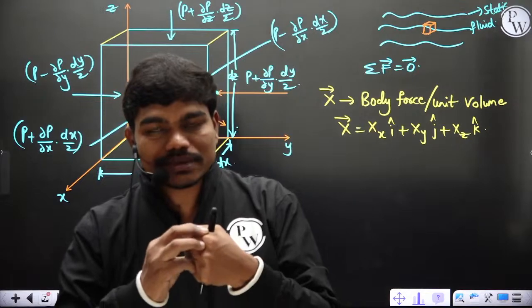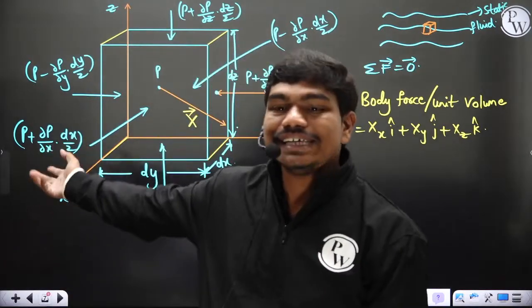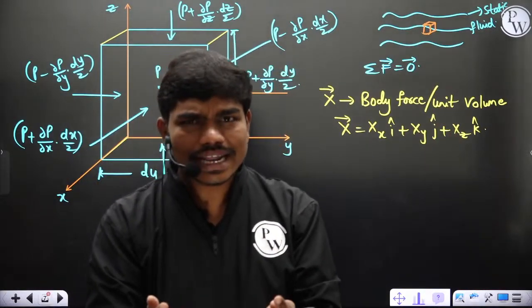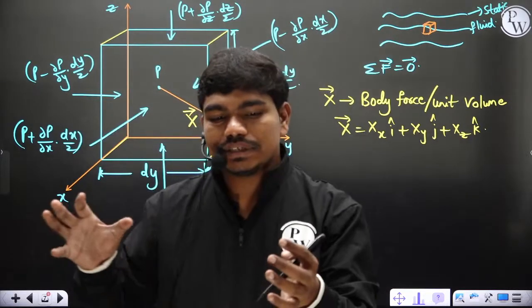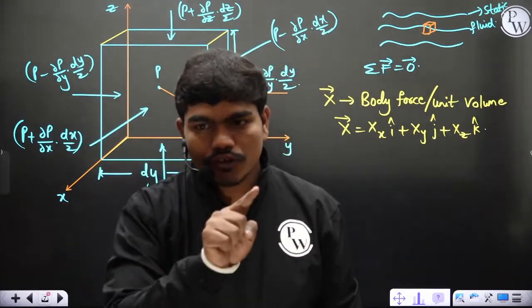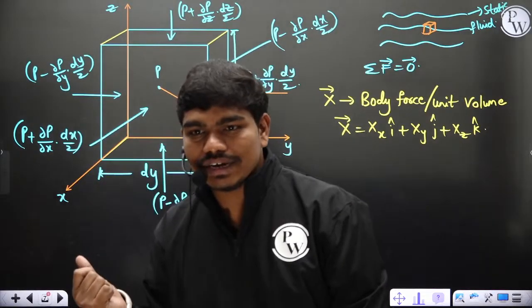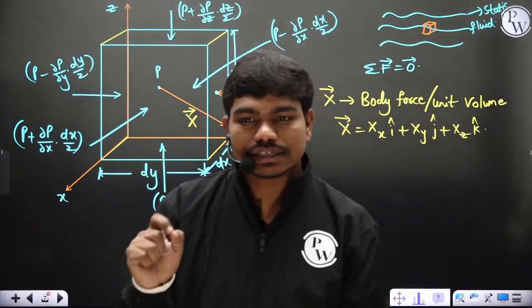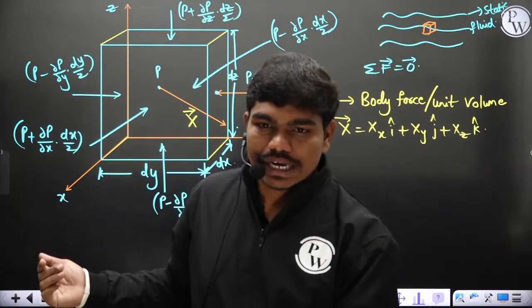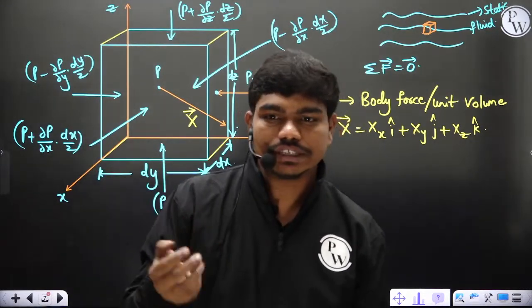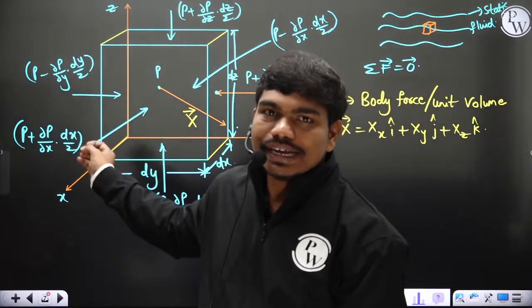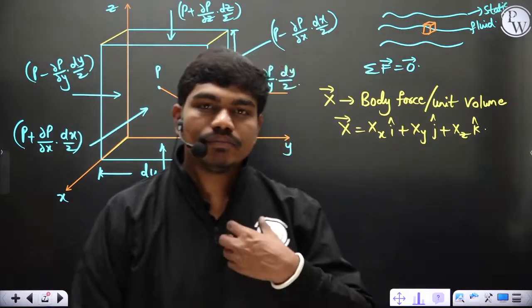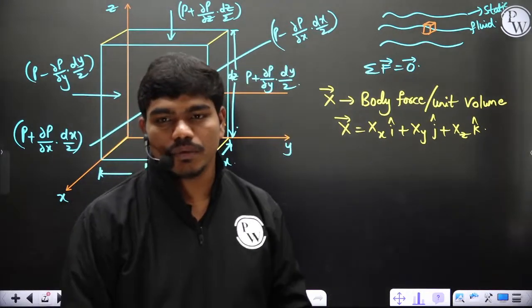Okay, so whenever the fluid is in a magnetic field, for example, let us suppose this is some molten iron. Let us suppose I have taken a big ladle of molten iron, then let us suppose I keep some magnet close to that. This static fluid of molten iron is exposed to some magnetic field, yes or no? Then the magnet will exert this magnetic force at each and every point in the molten iron, correct? That is how some fluids can act. Similarly, in case of piezoelectric, the fluids can be experienced to certain electric fields. So clearly, sometimes this fluid can in general have a body force which is acting at each and every point. Clear to all of you? That's why I am generalizing. This is the body force per unit volume of the fluid actually.